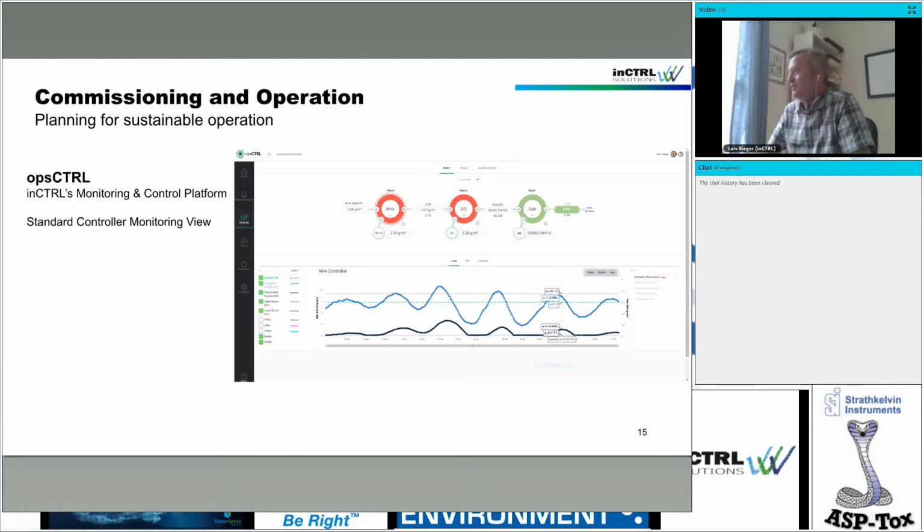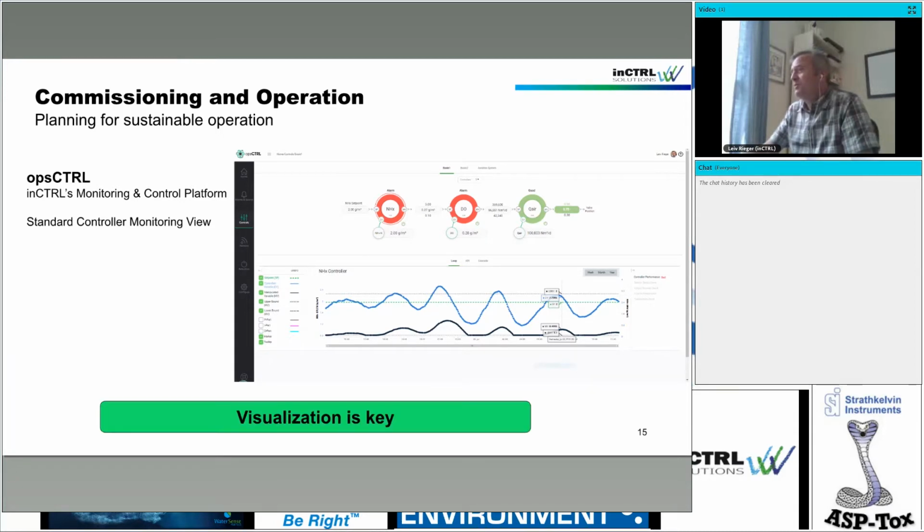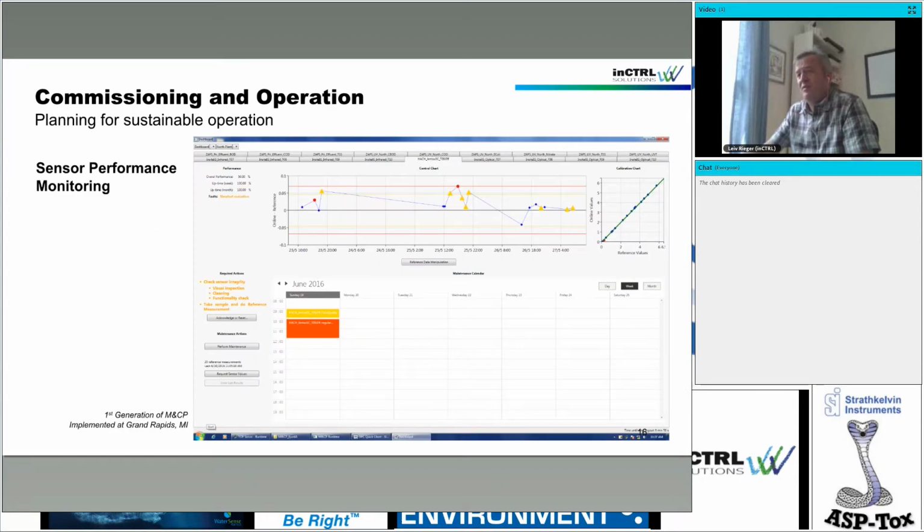And then they have the option to actually check every single control loop. And at the bottom, you see again, so this is the green is the set point, blue is the controlled variable, in this case ammonia, and black is the manipulated variable. Not well performing, so you see that bad. This actually tells me that with better tuning, you would improve the performance of that system. Yeah, so visualization is very, very important to make the system, control system, work after commissioning and not just switched off.